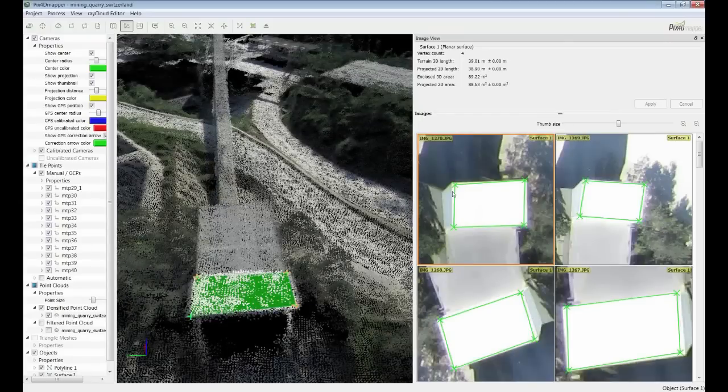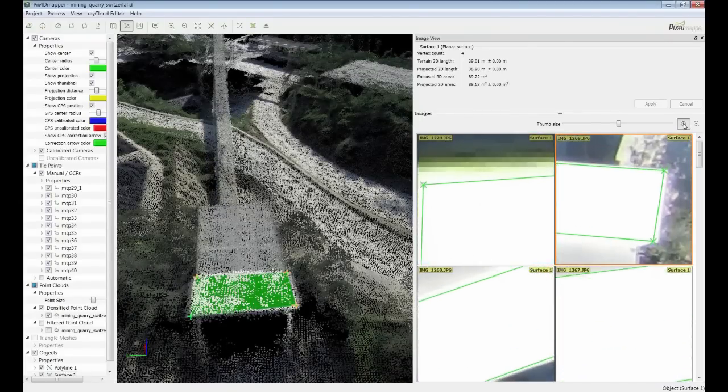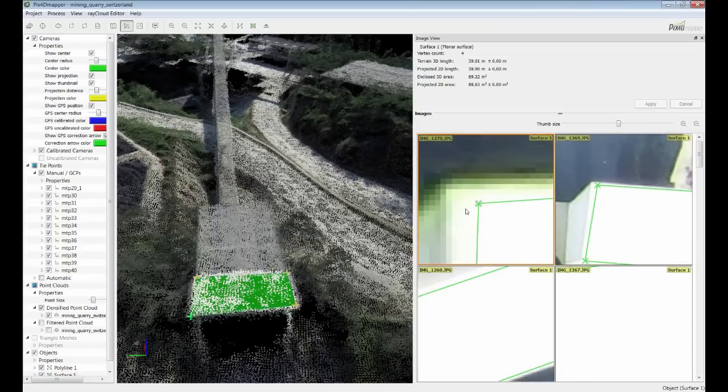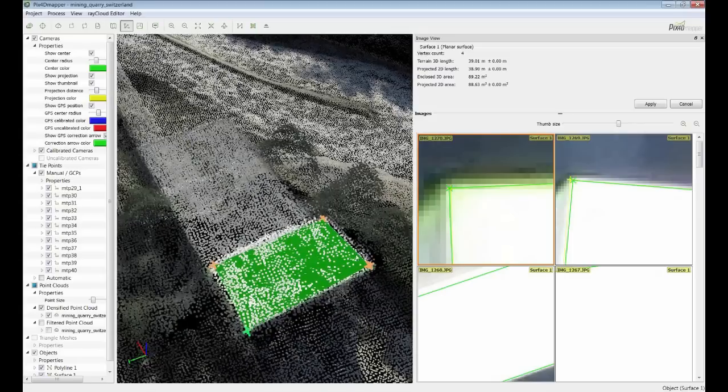Again, in this case, you can refine your measurement by zooming in on the images and adjusting the corners to be exactly on the image content. This allows you really to go for pixel accuracy measurements of lines, points, and also surfaces. If you have more than 3 vertices in your surface, this surface will be triangulated and then a plane will be fitted to each triangle.